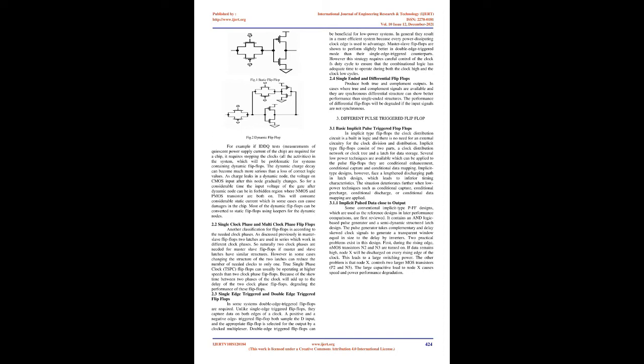because the skew time between the 2 phases of the clock will add up to the delay of the 2 clock phase flip-flops, degrading the performance of these flip-flops. 2.3 Single-edge triggered and double-edge triggered flip-flops.